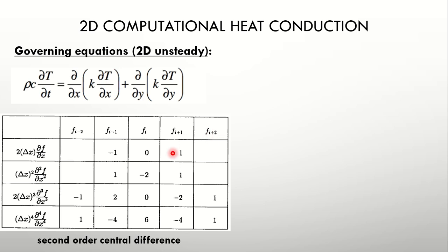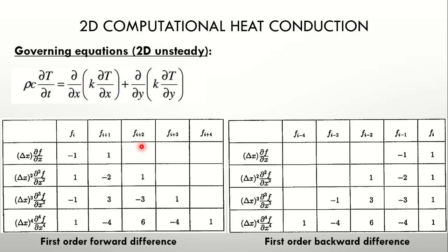So that is why we don't do a central difference, we do a backward difference. For example, if I want to find the temperature at the n plus 1th time step, I go back to the first order backward difference. So t at n plus 1 minus t at n, because I am finding at n plus 1, not n. So it will be t of n plus 1 minus t of n divided by delta t. That is how I do it.